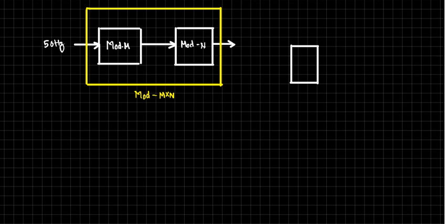Before starting the counter and shift register, we had written some points, look. Each flip flop acts as a what? Frequency divider. What is the division factor? Each flip flop is acting as a divide by 2 frequency divider, right? Or you should not go with the flip flops, you should go with the states, because sometimes states may be deleted. We may not go for complete states like from 0 to 7. If it is a 3-bit flip flop, we may limit ourselves to 0 to, let's say, 5. In that case frequency will be divided by m.